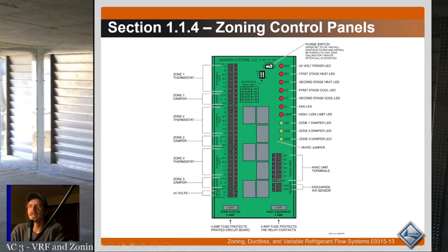Sometimes all the thermostat connections are on one side and all the dampers are on another. A lot of times it's set up just like this. And you'll have a common for the damper, and then power closed and power open terminals. Again, generally you're going to be using those power closed terminals. So you'll have common, power closed going to your dampers, and then all your thermostat connections go back to here. And on most modern systems, basically this zone control is what's going to determine whether or not the system goes into heating or cooling, which is why you have all the connections here.